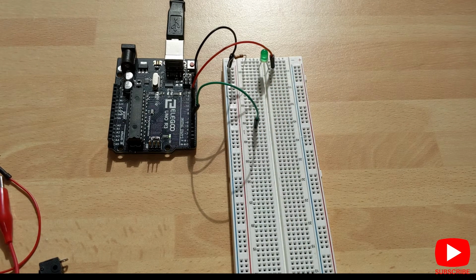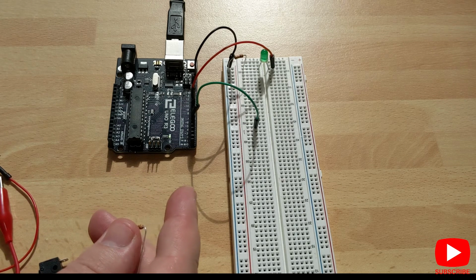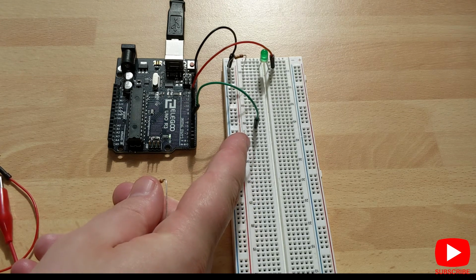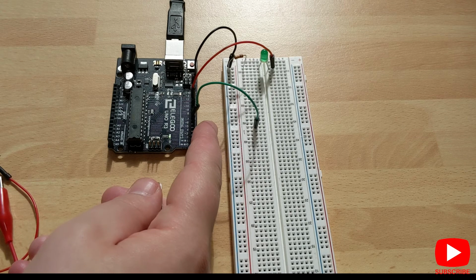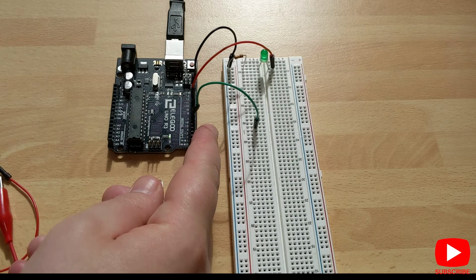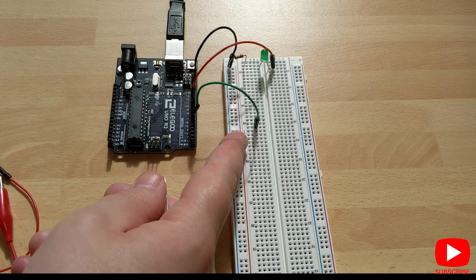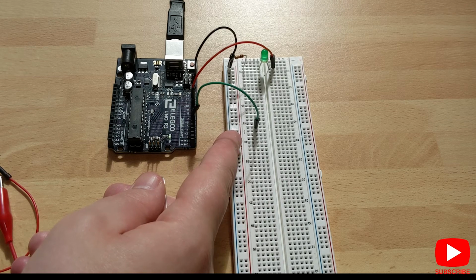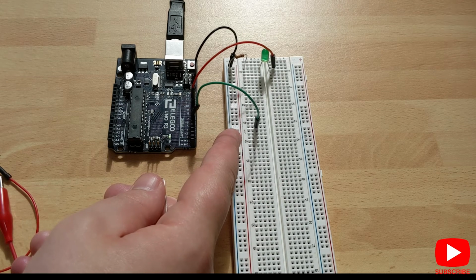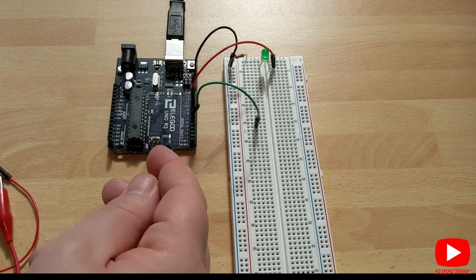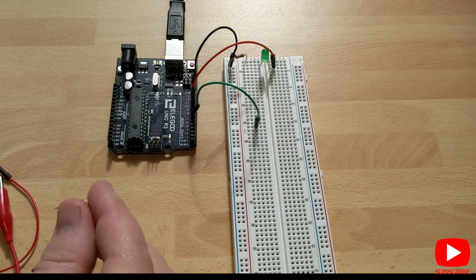Now what we need to do with pin 6 is pull pin 6 to ground. So what that means is we need to put a 10k ohm resistor on pin 6 onto ground. And that means when we're not applying 5 volts, when we're not pushing the button, the pin is pulled all the way to ground. If you don't do this, the pin doesn't get pulled all the way to absolute 0. It kind of floats around, and you'll get some results that aren't desired. Basically, the LED in this case may or may not turn off, or it might flicker.